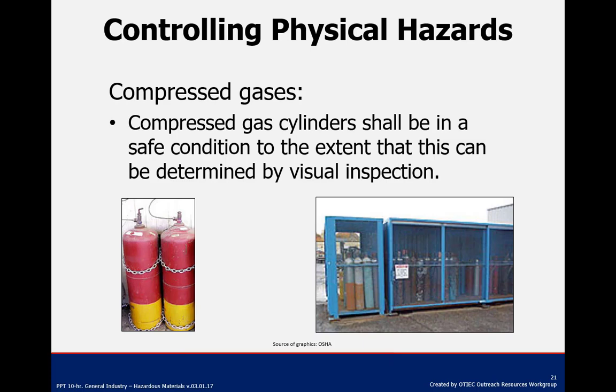Cylinders should not be kept in unventilated enclosures such as lockers or cupboards. Ensure cylinders are stored and used in a dry, well-ventilated area. Cylinders should be stored outside of direct sunlight and heat. Do not tamper with the safety relief device in the valve or cylinder or attempt to repair or alter a cylinder valve or safety relief device. Cylinder valves should be closed at all times except when cylinder is in active use.